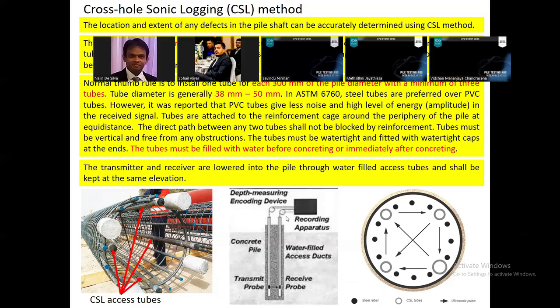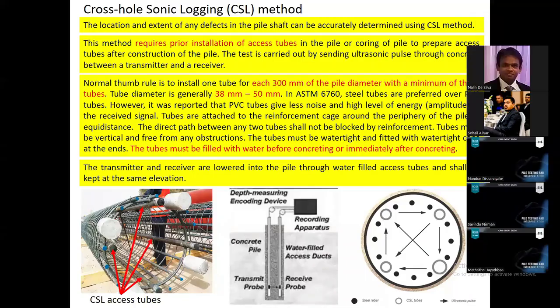What we do is lower the two probes. One of them is sending the ultrasound wave, and the receiving probe will receive it, right? The data logger will record the wave arrival.